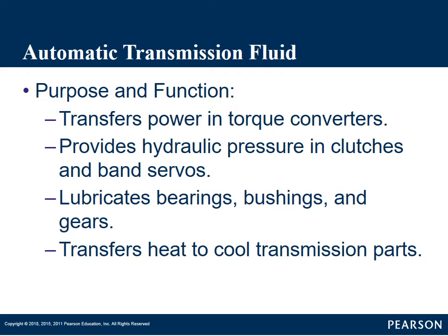The main purpose or function associated with transmission fluid, there's actually a list of them. Obviously, it transfers power in torque converters. This fluid is what actually allows the torque converters to work, and you'll understand that better when we go through torque converters. Without that fluid pressure, torque converters don't operate, and we don't have any power transfer from our engine into our transmission.